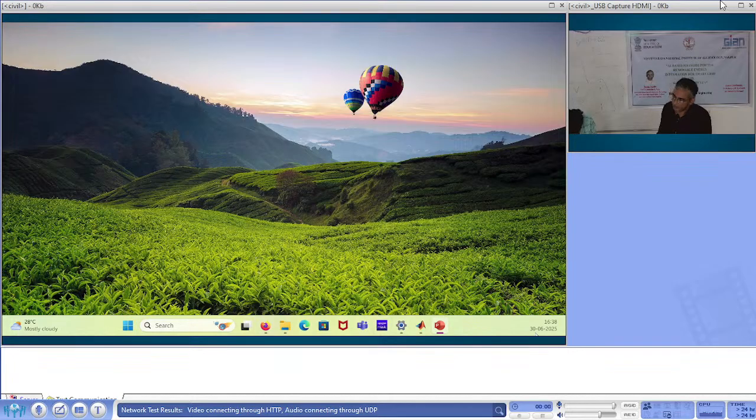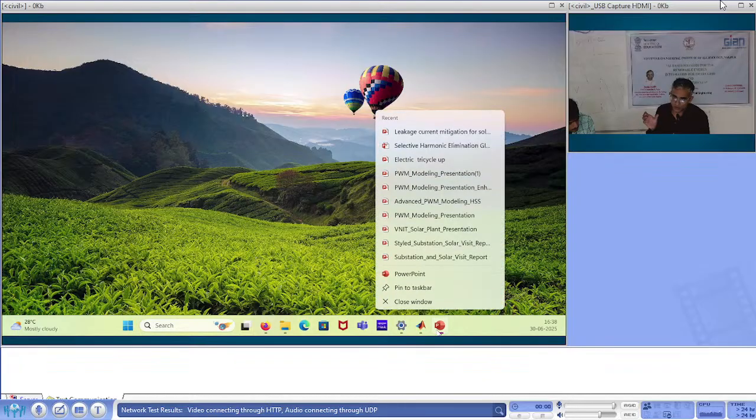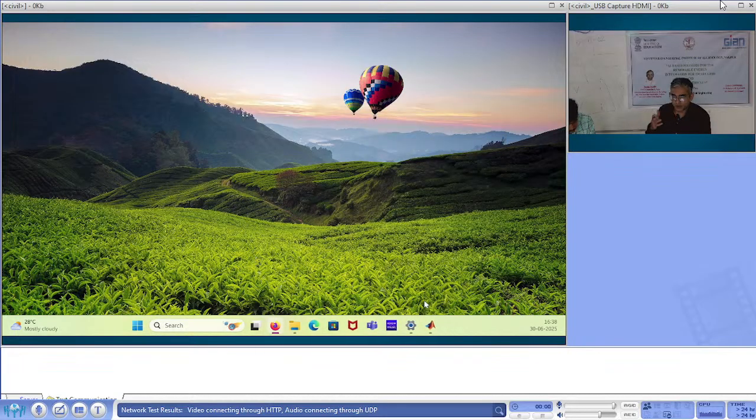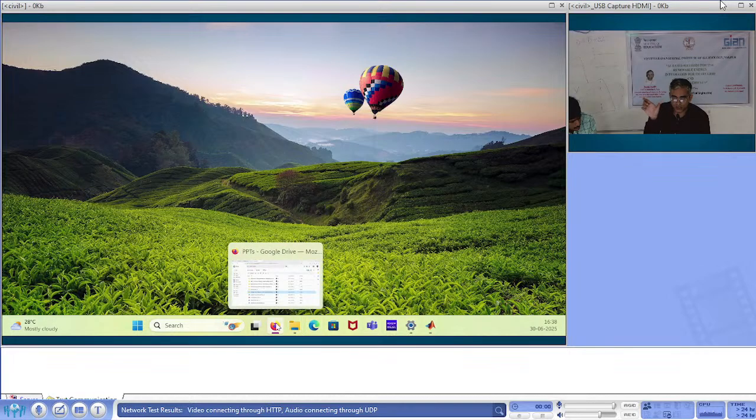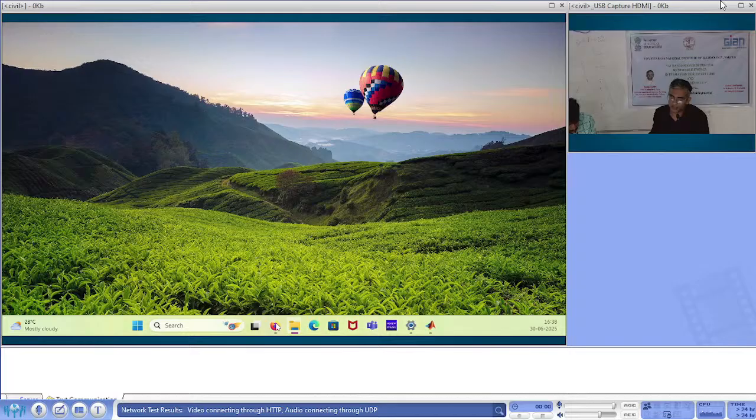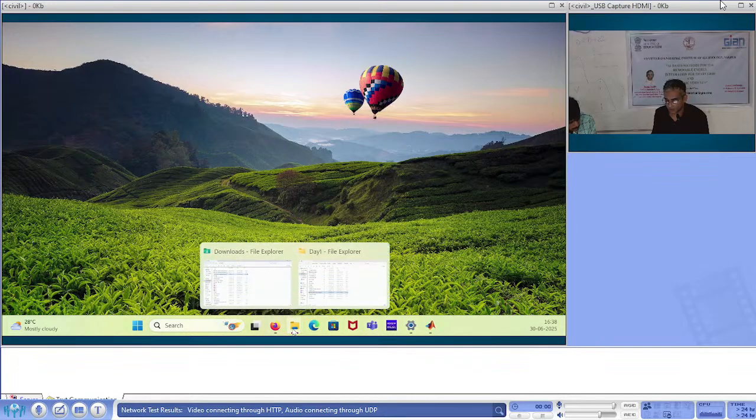And one more advantage is that it is also amplifying the system because it is acting as a boost converter also. If you remember the circuit of a boost converter, there is an inductance and that will boost the voltage. So here also there is a boost inductor and that will help in amplifying the voltage. So these two advantages are there for the current source inverter.